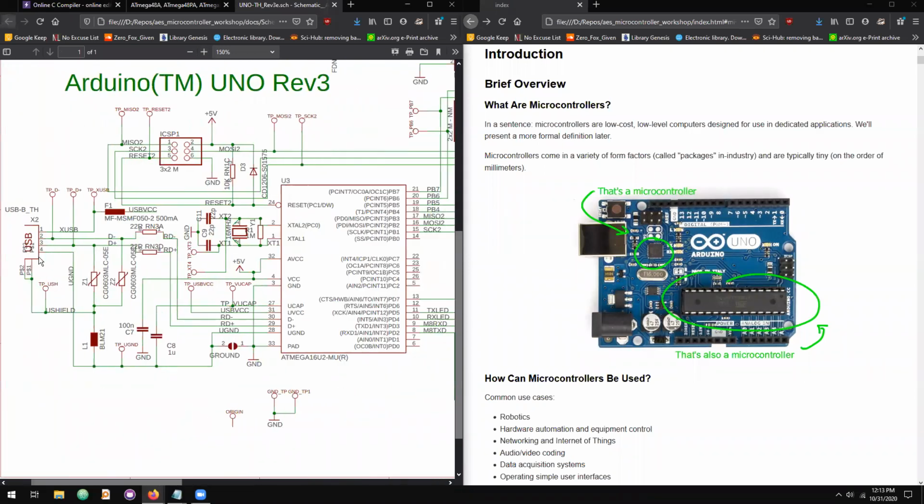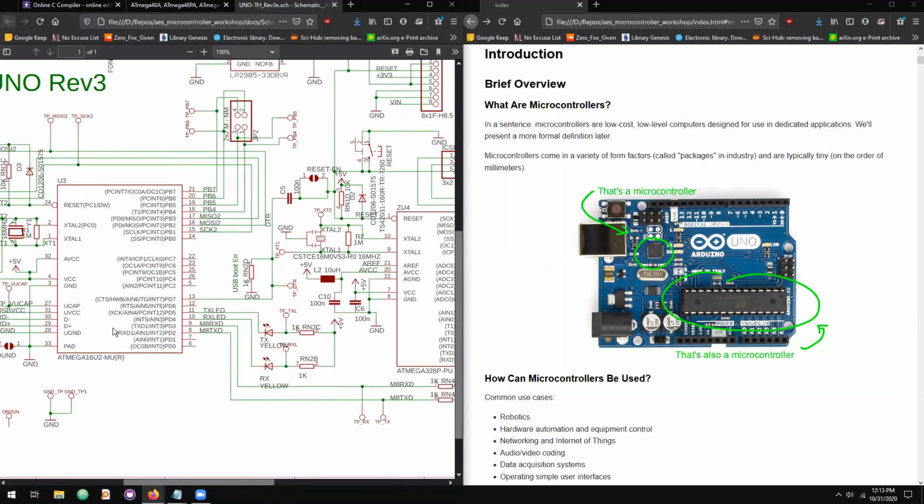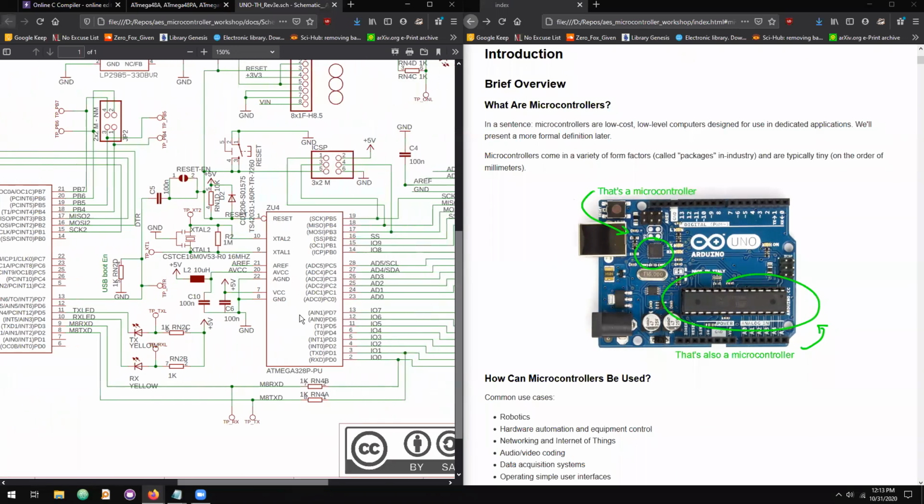Here in the electrical schematic, we have our USB signals, data positive and data minus, fed into this secondary microcontroller. This secondary microcontroller then takes action based on the information that's communicated to it, and it drives the reset signal on our target.